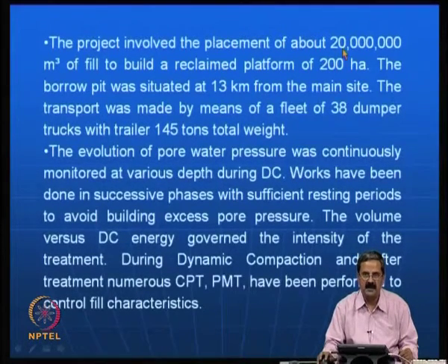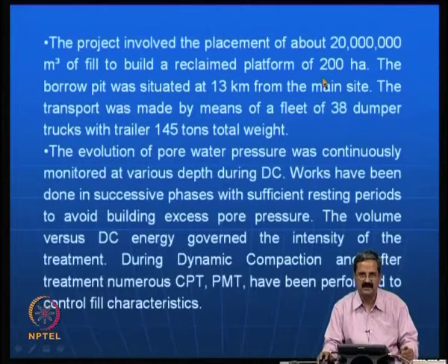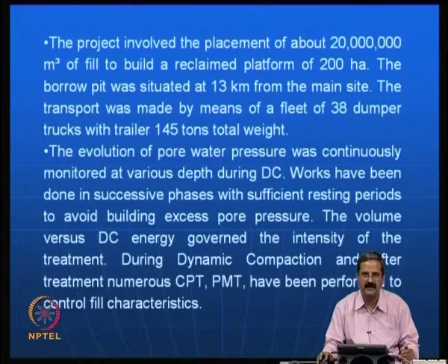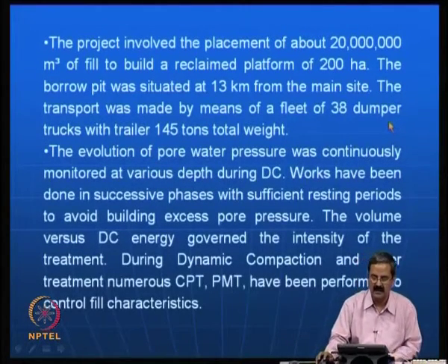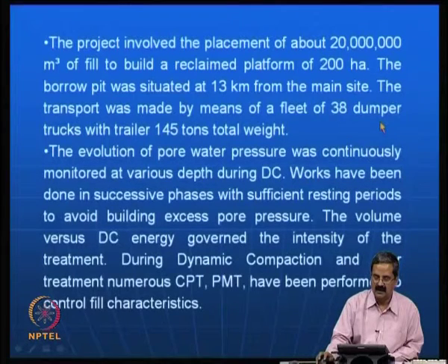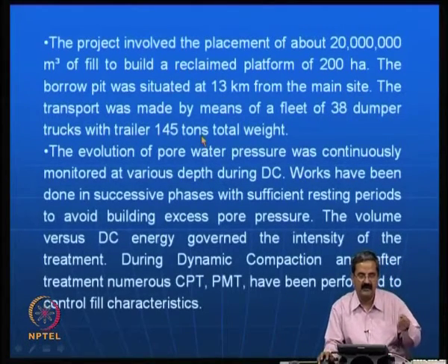So what they did was that they had to place about 20 million cubic meters of fill, the quantity is so high, to build a reclaimed platform of 200 hectares. Imagine that an area of 200 hectares is quite high. The borrow pit was situated at a distance of 13 kilometers from the main site. The transport was made by means of a fleet of about 38 dumper trucks, going over the distance of 13 kilometers, with a trailer weight of 145 tons, the weight that they can carry.